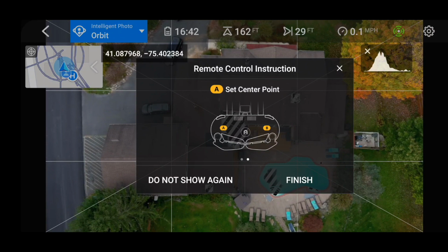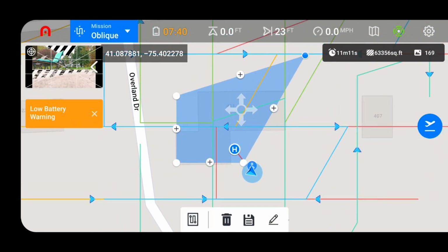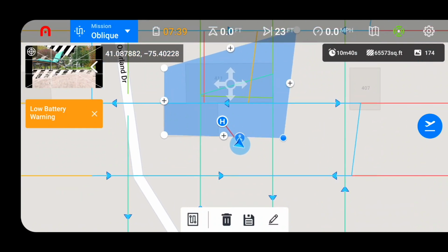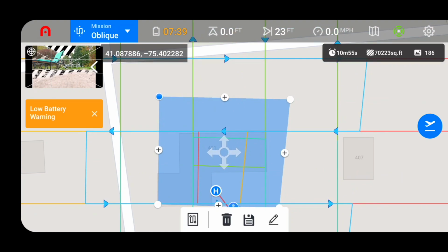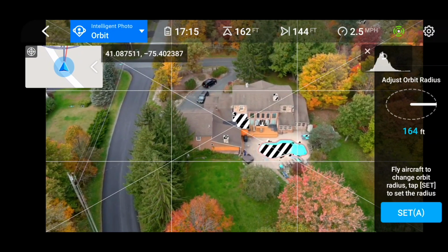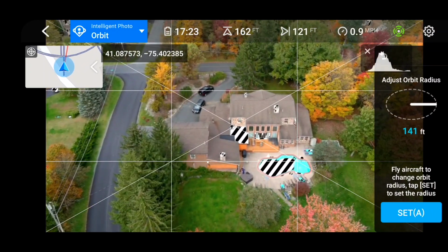the structure. If you are considering modeling a larger structure, such as a commercial building, consider using a rasterized flight instead, but remember to tilt your camera to capture those vertical features during the flight. For the Autel, point of interest mode can be almost entirely automated, which makes the process a breeze.